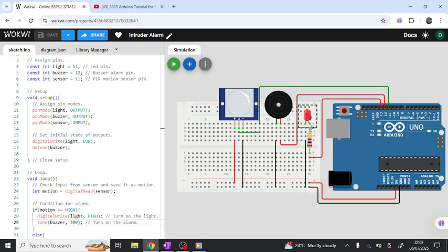Okay, so that's the anode. Then of course the negative side is connected to ground of this guy. So look at this breadboard. I just connected everything here to ground. This line here, are you seeing it? All this line is connected to ground. So anything in the breadboard that connects to this place is connected to the ground of the Arduino.